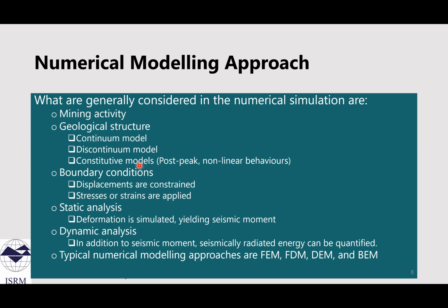Frequently the numerical modeling approaches are combined with field measurement. The waveform obtained from the seismic monitoring systems can be analyzed to obtain the seismic source parameters, such as the seismic moment, radiated energy, seismic efficiency, slip rate, and so on.